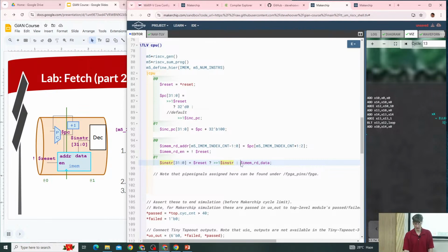It's all fine. It's not wrong. It's also not necessary. We're only going to use the instruction bits if we have a valid instruction. So there's separate logic that knows if our instruction is valid and is deciding whether to operate on it or not. We can allow the instruction to be whatever in the cycles that are invalid. And that's consistently the methodology that we would use.